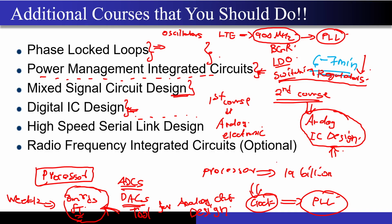Those particular curves are not only useful for this course. If I tell you to design a current steering DAC, that is a digital to analog converter, or a flash ADC, or some circuits like this, you would have to go through those plots. Unless you have these plots characterized for that particular technology node, it will become very, very hard to design the ADCs, DACs, or even the phase lock loop circuits, the charge pumps, the frequency divider and all. This is what I am talking about. Correct? So please make sure that you study the week 12 transistor summary lecture to such a depth that you don't have any doubt left. Correct? If you still have doubt, please go to the internet and study about gm/ID design.